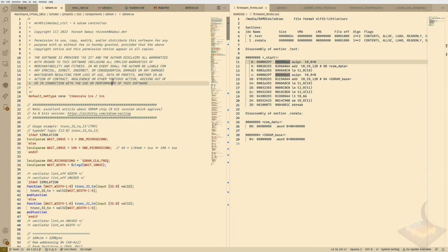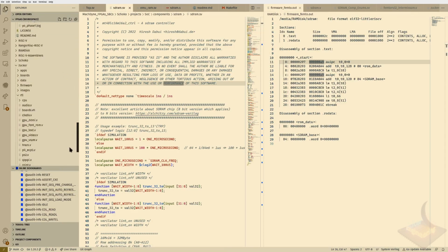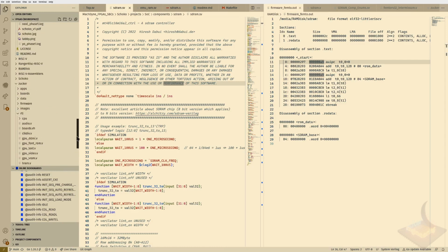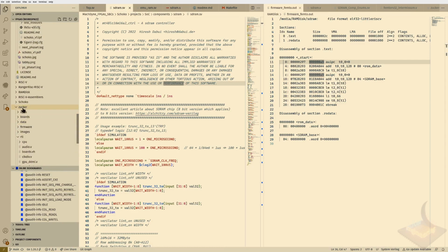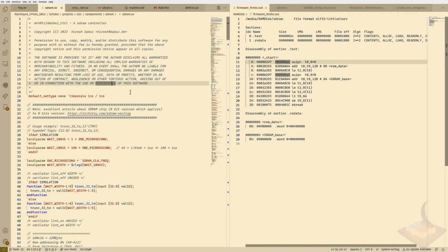Now let's look at the core of this simulation, which is the SDRAM controller itself. And it's been borrowed from the Zucker project, which is listed down here below. I pulled it out of this project right here. So inside this Zucker project is the code that came from Machdyne that shows how to use their boards. And so I'm adapting their SDRAM for the Femto, which acts a little bit different than the Pico that they used. So we'll start at the top here.